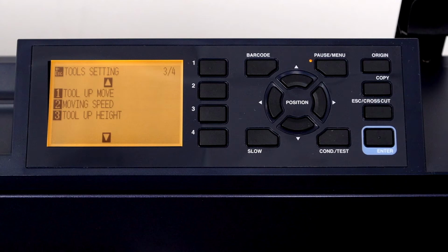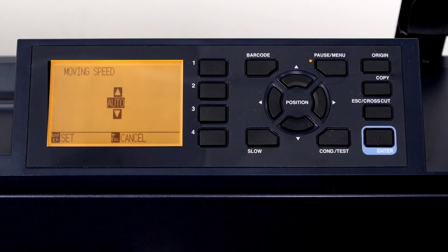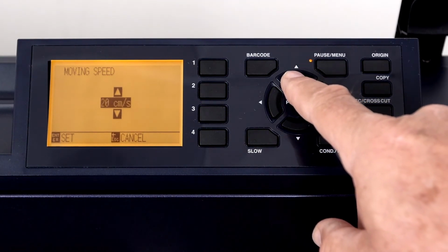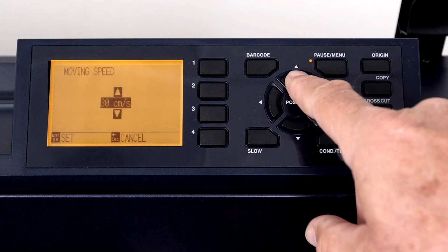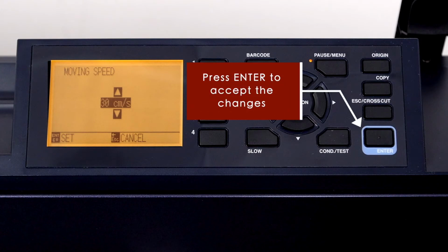For instance, if we wanted to change the tool move speed, we would press the 2 key. This gets us into the tool move speed setting. Here we can either increase the value by pressing the up arrow key, or decrease the value by pressing the down arrow key. Once the settings have been changed, we can accept the changes by pressing the Enter key.